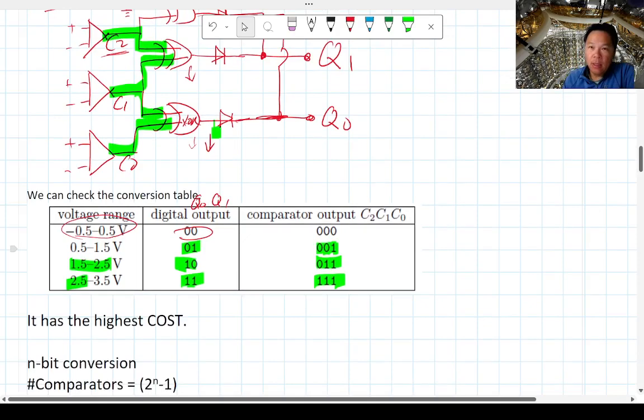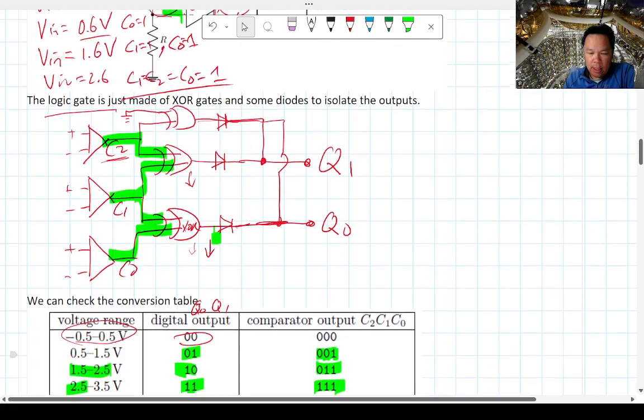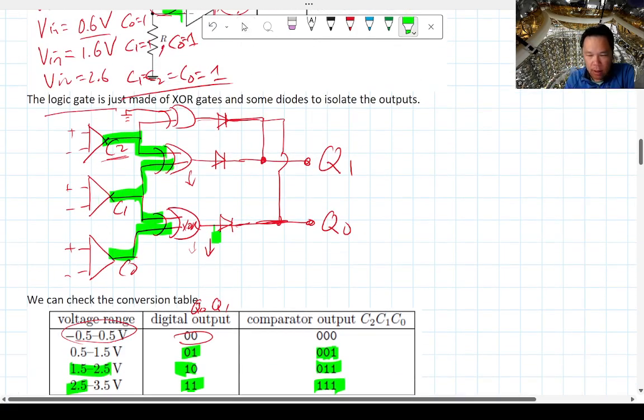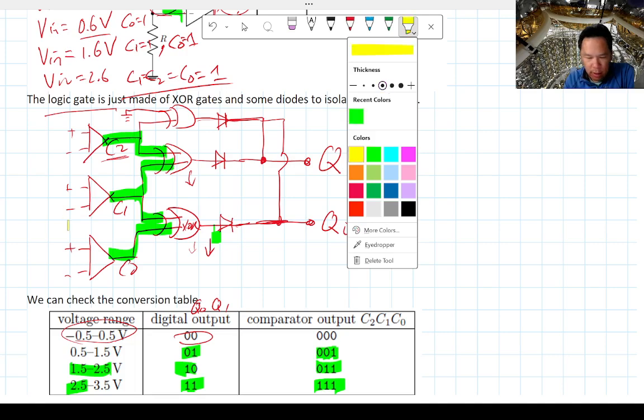So this is really neat, right? Conceptually, the logic is very simple. And the cool thing is that it's very fast. As soon as the signal on the left-hand side changes, any change is basically propagated at the speed of light to the right-hand side. Depending on how long the wire is, if it's only a few centimeters long, and then you have to go through this gate, which has a little bit of propagation, on the order of maybe fractions of a nanosecond, you'll have your output in nanoseconds.